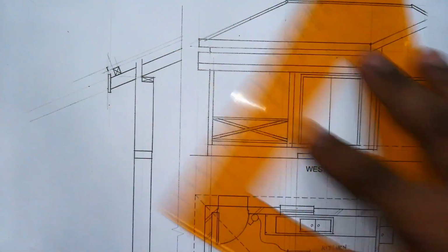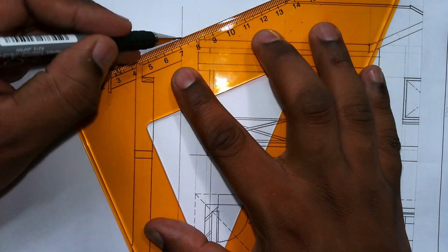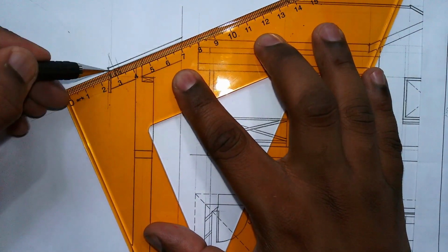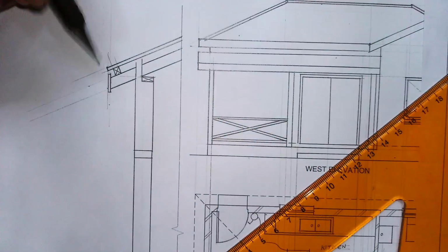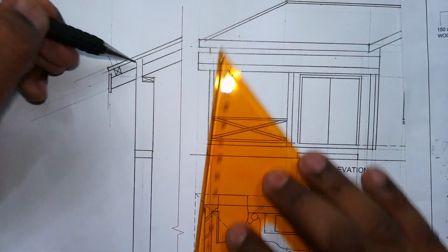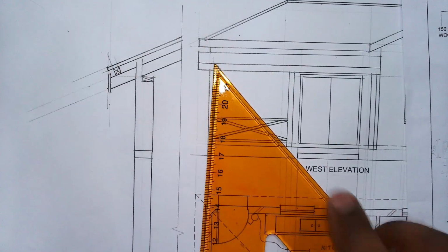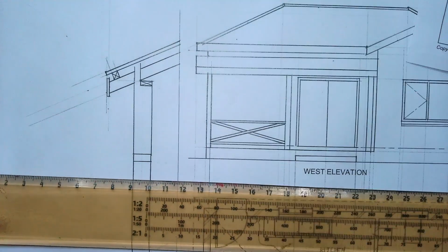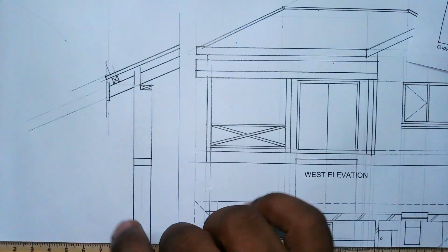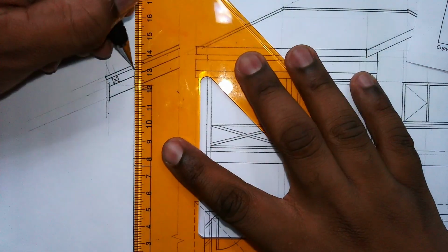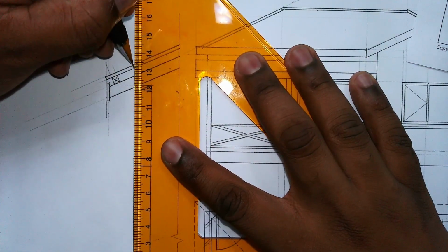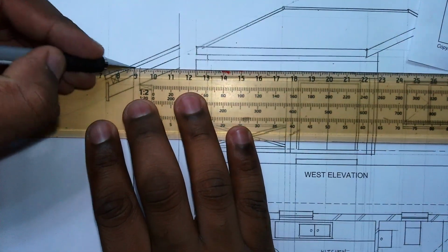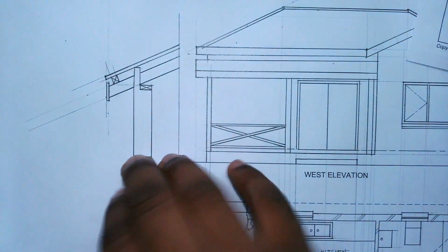All right, and then I can just draw in those 2 solid lines like that, just like that. So this is the roof sheet there. Okay, and then now I can just complete my wall there. So what I want to do is I'll slide my T-square up, but first of all I have to extend this line first all the way to the roof sheet there. Then from the roof sheet I'll just draw a horizontal line like that.